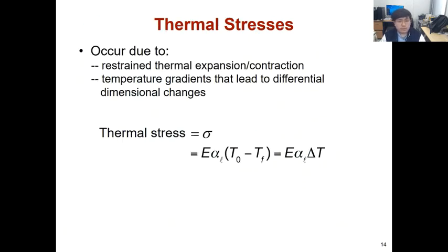Based on our thermal characteristics, we can also define the thermal stress. It is because stress is simply linearly proportional to the Young's modulus and strain. So we define the thermal strain, and when those kinds of strain can be expressed by the thermal strain, at that time we can say that this stress is a thermal stress. But please remember that the free thermal expansion does not generate any stress.